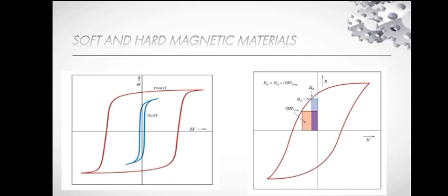Again, hysteresis behavior is related to the ease with which the magnetic domain boundaries move. By impeding domain motion, the coercivity and susceptibility are enhanced, such that a large external field is required for demagnetization. Furthermore, these characteristics are interrelated to the microstructure of the material.